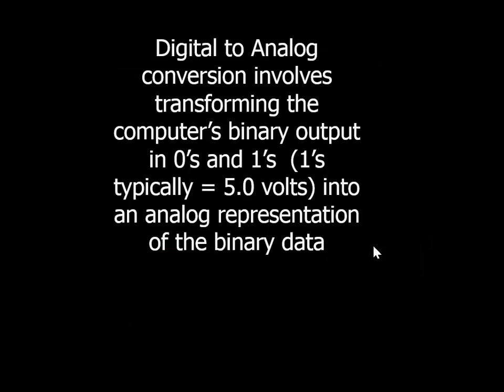So typically it's 5 volts. This slide is a little dated. Our processor typically is using a 3 volt reference or a 3.3 volt reference. We could set up our reference voltage on our A to D to whatever we want. And as we get into more of the detail of our 8051, we'll see that there's a pin that we select our input, or we can tell it to use VCC as our reference. But whenever we do analog to digital or digital to analog, we have to select a V reference.